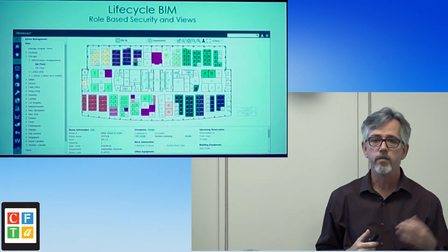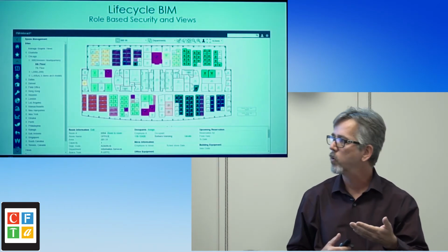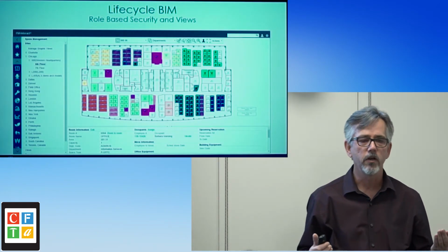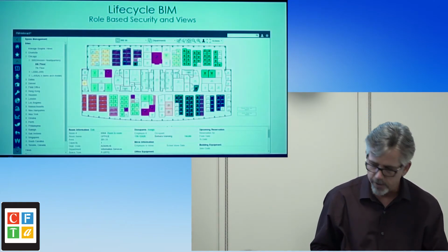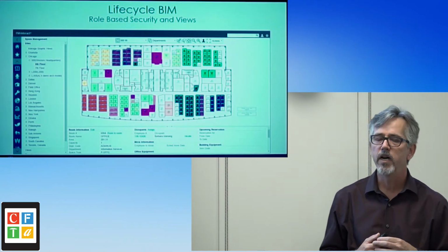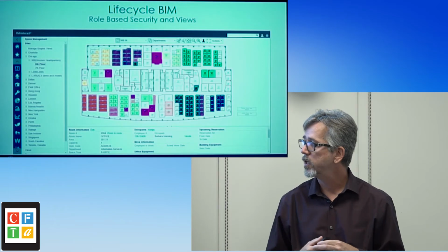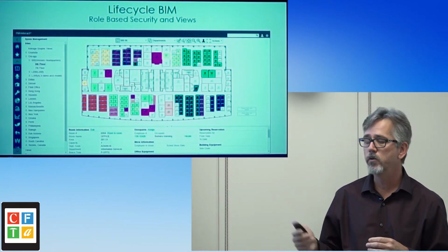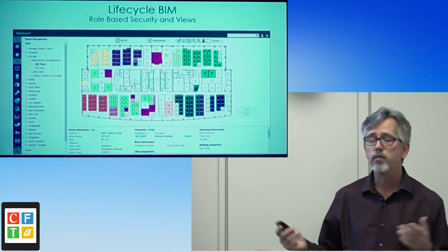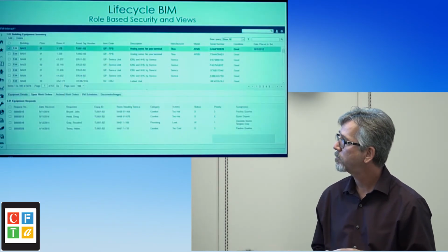It's just a view of a model that's sliced down through the floor plan at 4 feet above the finished floor. It's the typical way that we look at floor plans. We slice them, we look down. BIM tools have the ability to do that really easily, whereas in most CAD environments, you have to sort of draw each one of those. So this is a view of a model, potentially with the ability to get all of that rich data out of there.